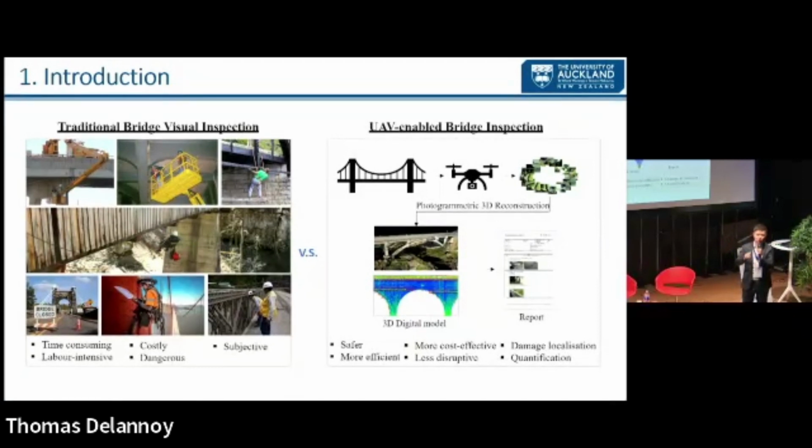Currently there are 2 ways to deploy the camera-based drone for inspection. The first one is that you can take individual images and then do the analysis to understand if there are any defects, like cracks, in the individual images. The second way sounds a little bit premier: we use photogrammetric 3D reconstruction.